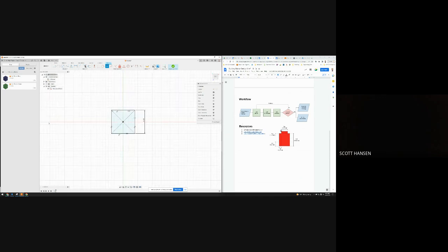Let's start with the little peg on the top. If I'm looking at this block from the top-down view, I'm just going to see a circle for that peg. So let me create that circle. Let me choose my dimension tool, click the circle, and the diameter of that circle in this case is going to be 3 P units. So let me type 3 times 1.6. That'll resize that circle.